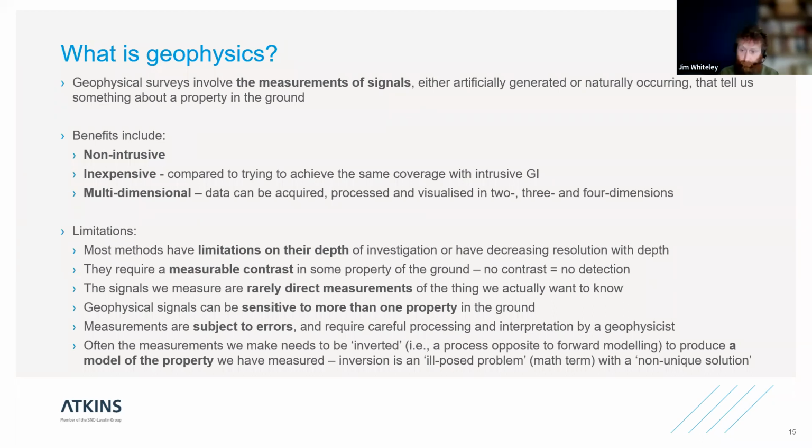And so on that, I think it's important that with some of these methods where you're producing this model of the ground, that it is exactly that. It's a model. It's not a direct measurement in many cases. So whenever you see a seismic refraction survey, whenever you see an electrical resistivity tomography survey, as we're going to talk about later, what we're generally dealing with are models of the data rather than direct measurements themselves. So the phrase I think I need to get tattooed in my head when I talk to people in my office is that the map is not the territory. We're not actually taking direct measurements of the ground. We're producing models. And I think that's something that's not particularly well communicated by geophysicists.